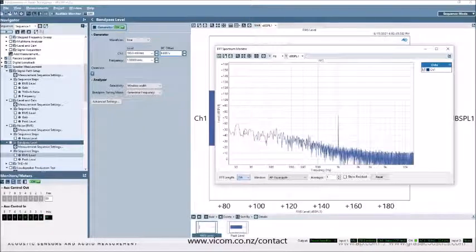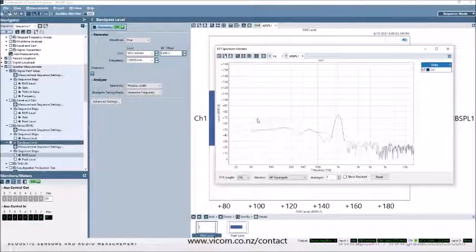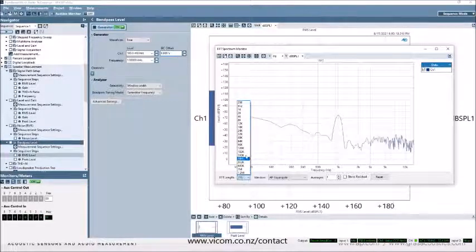At the other end, I could make this incredibly short, and it will update very quickly. But notice that my 1K signal there is really spread out. I have very low resolution, and there is a 0 hertz function in FFT, and that is bleeding over into the upper frequencies. So there's a trade-off in resolution versus time with our transforms.